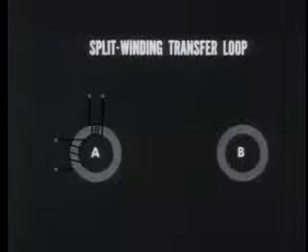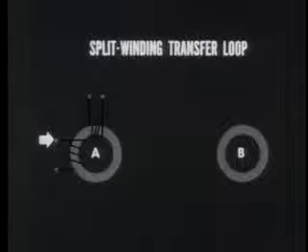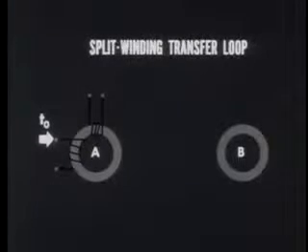We'll add 2 input windings first. The input on the left is connected so that the current flows into it on the non-dot side only. This is the one that our logical diagram showed as coming in at time t0 and setting core A to binary 1. At the top, current comes in on the dot side, setting core A to binary 0, and the time is t1. There is also an output winding at core A, and like those in the single diode loops, this output has more turns in it than the input windings have.